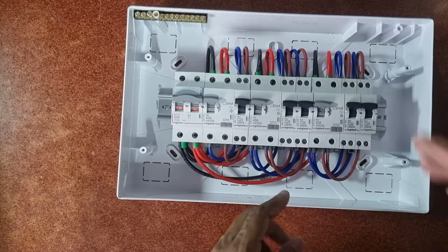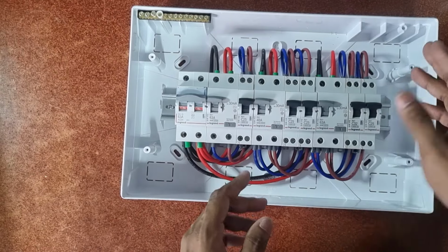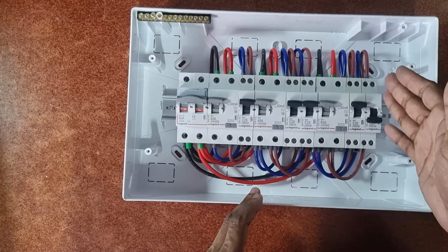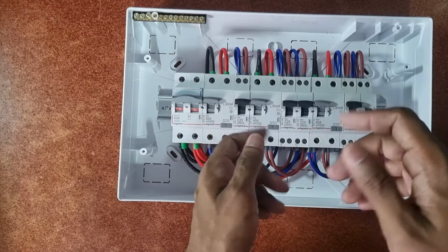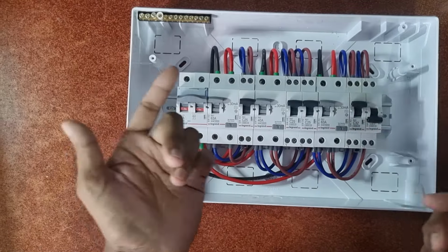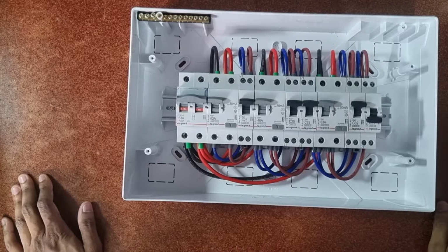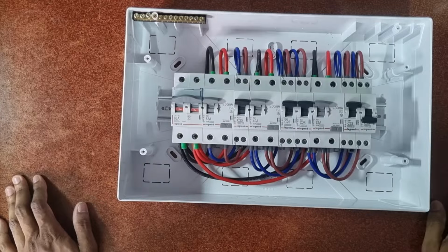Then if, like I say, there's a problem in the room, I will check only this line. So let's say the kitchen is faulty, so switch off the kitchen. I'll check the outlets or the lighting. Then it will be very easy to find the fault instead of with other types of electrical wiring.